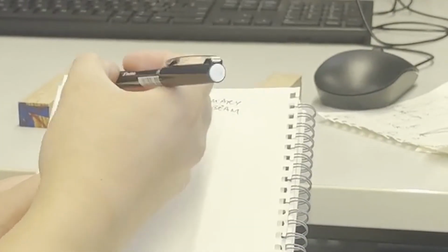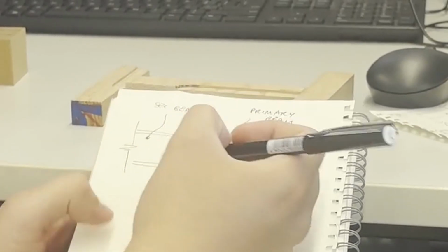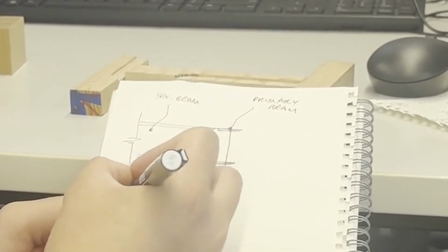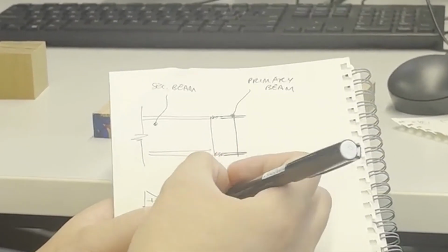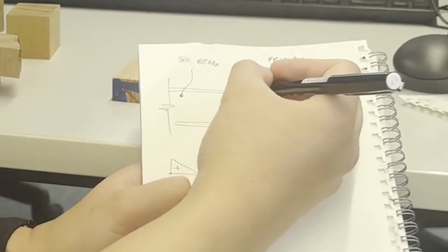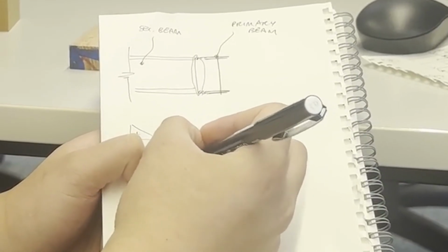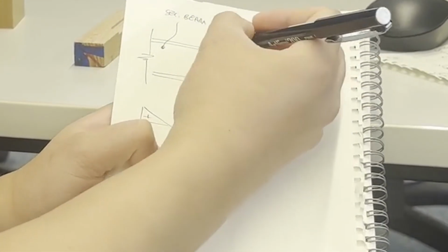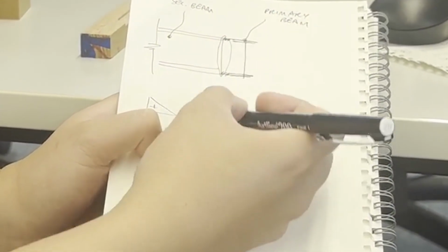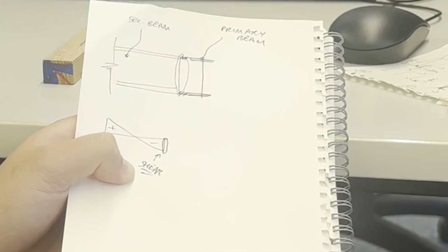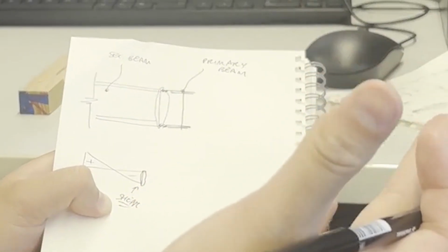firstly, remember the shear force diagram. I didn't draw it very well, but this secondary beam shear force diagram, remember it looked like this, okay? Plus, minus. So here, at this interface, you have the largest amount of shear. So basically, these welds are taking all that shear. That's called a shear connection, right? And we'll talk about that in week 8.